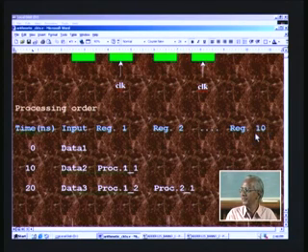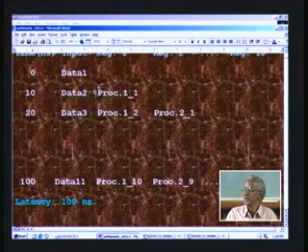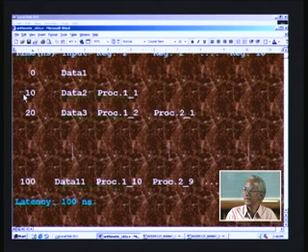So, naturally at register 10 if you examine the output, you will get the final result, and while this is happening, at every instant of clock you will be reading a fresh data, data 1, data 2, data 3 and so on. So, here at 100 nanosecond we have read data 11 and simultaneously processed process 1 corresponding to the data just previous, and the previous data of this is processed in the second stage, and so on it goes, and at register 10 is available the process output of process 10, which happens to be nothing other than data 1.